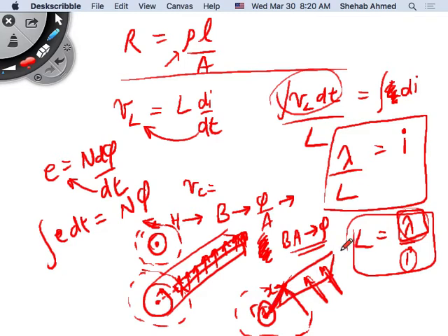And then this length here was dx, and sorry, the width here was dx, and the length of the conductor that I said was 1 meter, right? So we sort of multiplied after that. We took the B, the flux density that we got, and we multiplied that by basically dx multiplied by 1, right? So we integrated B with distance, right? That gives us what? That gives us the flux. This flux is linking the conductor, right?